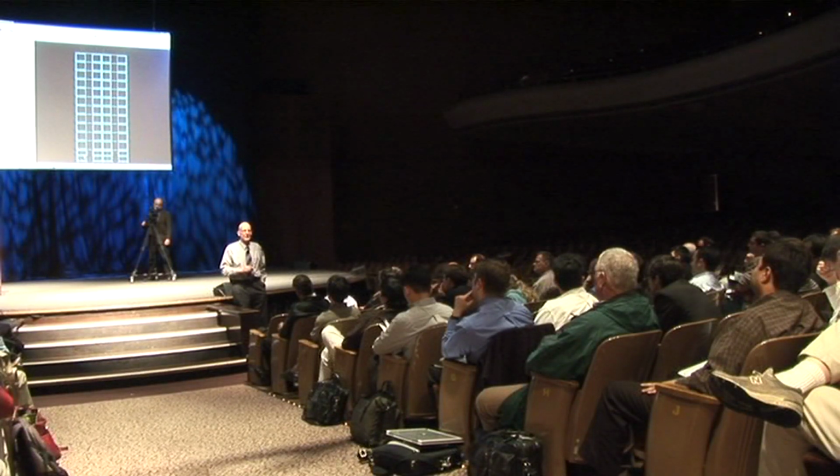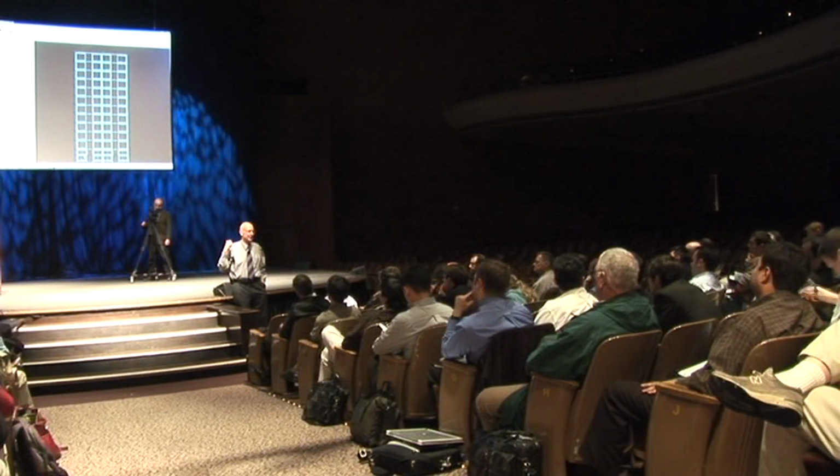Now, I suspect if you ran a more complicated case that it wouldn't be quite as nice as the example that I showed. But that's the way in which you should do it. And it's not a good idea to use a fine mesh and then use a strain in the worst element. That's way too conservative.